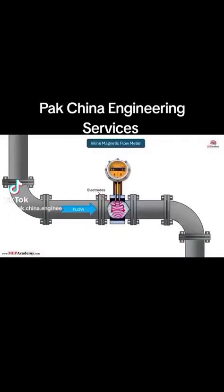Inline magnetic flow meter. Magnetic flow meters measure flow based on Faraday's law of electromagnetic induction. Two opposing magnets create a magnetic field that the fluid passes through. As the fluid passes through the magnetic field, the electrodes detect the voltage, which is proportional to the fluid flow. This flow meter will require electrical power or an onboard battery.